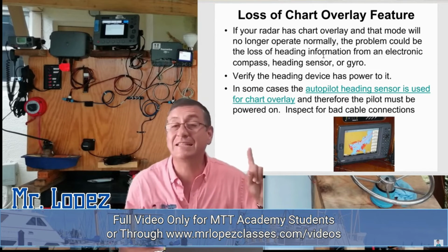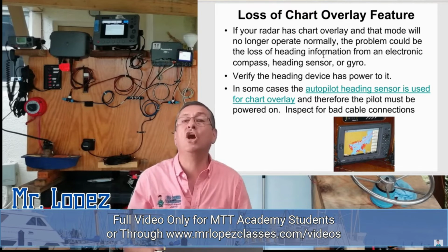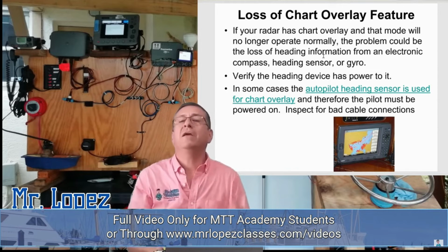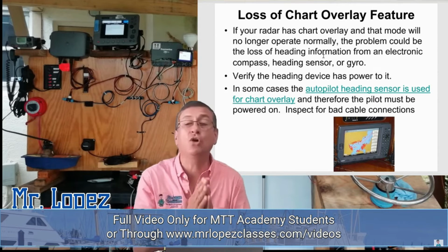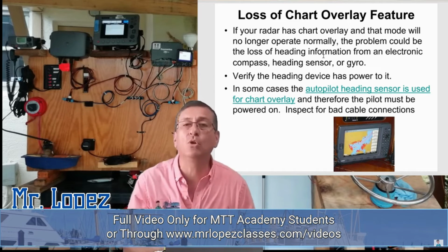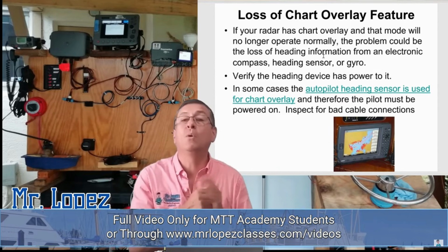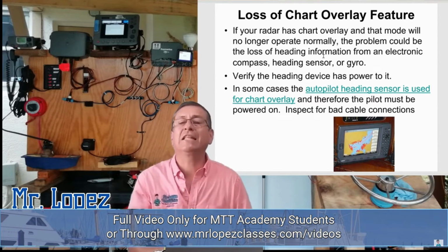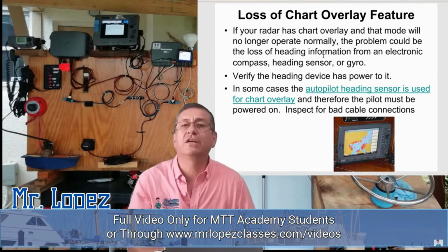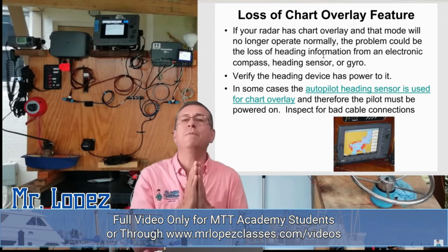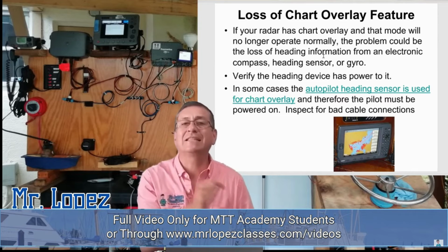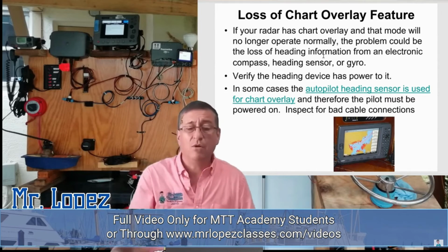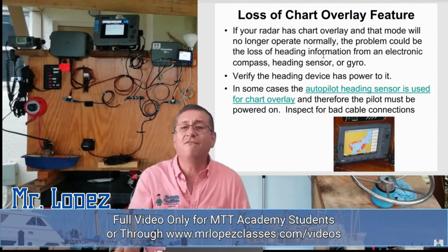Verify that that cable is not close to the antenna cables, to the VHF antenna. Verify that it is not close to, not together with, AC cables. It's not close to bonding or lightning conductors. Verify that that conductor is isolated from other sources of power. That's very important. It's critical for that sensor. The same goes for the radar sensor, but specifically with that sensor it is very critical.